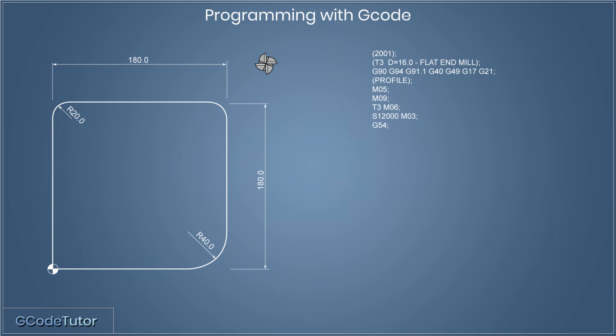G54 sets our working datum. This means within the machine controls we have already told the machine where our datum position will be, so G54 just tells the machine to read that information, so all our dimensions and measurements come from the datum position on the bottom left hand corner of the part.